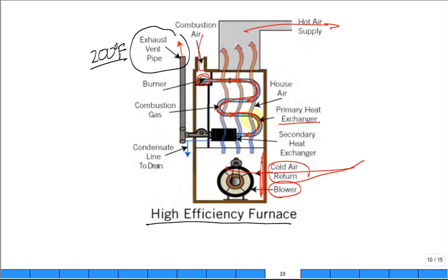But down here, after the exhaust gases have passed quite a bit, there's a special secondary heat exchanger because you can start to collect condensate. It's now cooled off the combustion product so low. And that's what you want. You want to get all of that heat out of it, transfer it to the air that's going to keep the inside of your house warm in the winter.